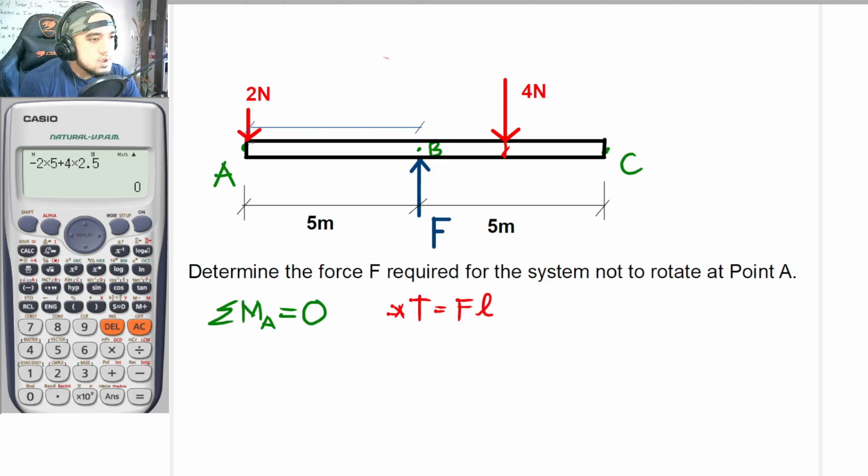So for this force, if this is now to be our reference point, by the way, my sign convention would be, maybe this time I would be using counterclockwise positive. As to why? Because, well, I just like counterclockwise positive. Okay, so with that, 2 newtons, this is for the first force, 2 newtons times, so what is the lever arm from A up until the 2 newtons? They are exactly at the same place, 2 newtons is located exactly at point A, thus this is now to be 0 meters. So this is now for the 2 Newton force.